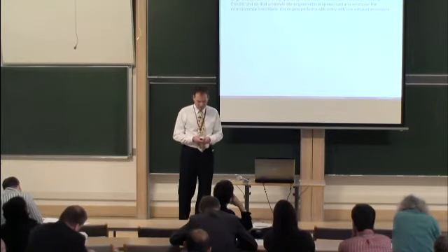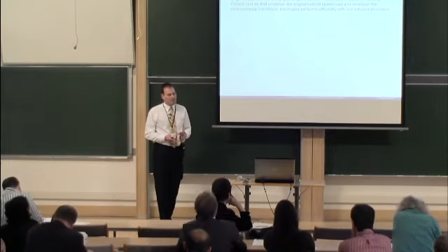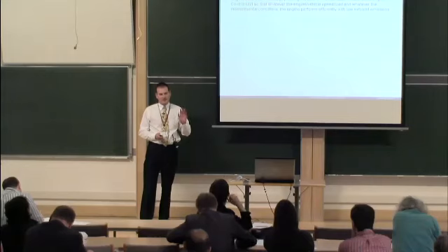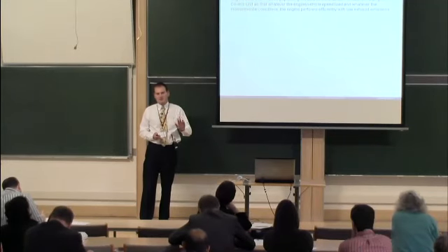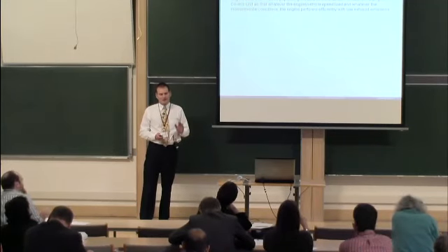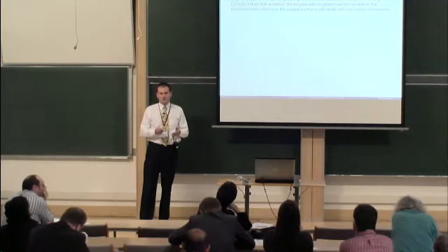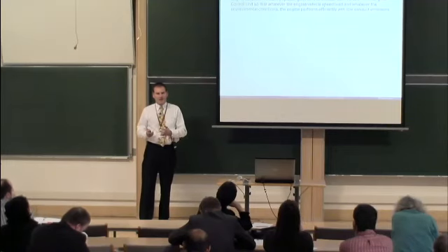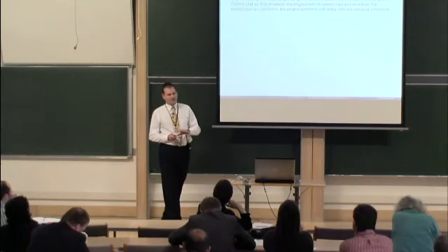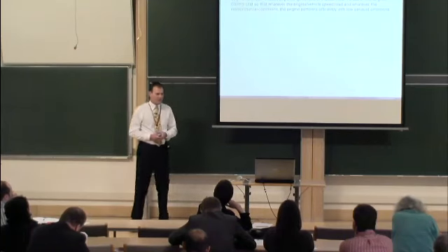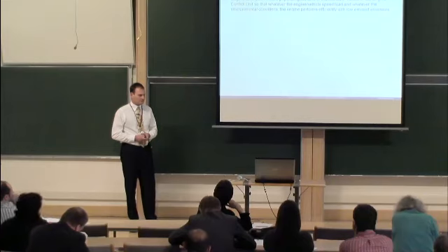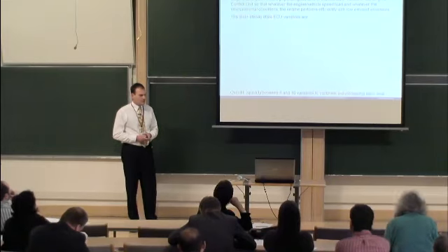Obviously some of those are more important than others, but they basically say that if you're at this vehicle speed, in this gear, with this driver demand for a certain level of torque, how much fuel to put in, what the air system will be doing, and any other emissions control devices. And that must work for all different speeds and loads, and environmental conditions across the board.